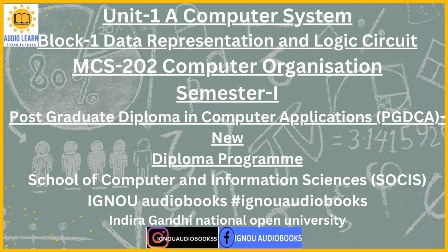Figure 1.8 shows the interrupt cycle. Figure 1.8, Instruction cycle with interrupt cycle. Look at the screen. Please note an important point in Figure 1.8, which is the interrupt enable and interrupt disable conditions. If the CPU is executing a very important instruction, the response to an interrupt can be disabled. In this situation, interrupts will not be processed or acknowledged by the CPU till they are enabled again.